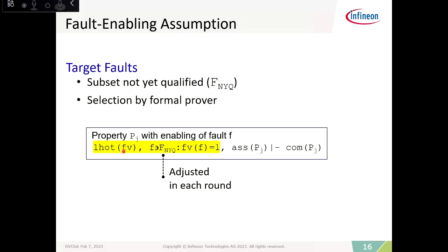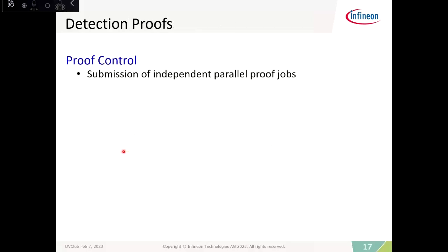The actual fault selection is done individually and very efficiently for each property by formal proof algorithms, which are highly optimized for the construction of counterexamples, each of which in our context shows an activated fault by which a property failure has been caused. This is the key difference of our formal flow to the normal Certitude heuristics. Before each detection round, we only select properties, but not property fault pairs. Thus, by exploiting advanced formal proof technology, we yield much faster progress.